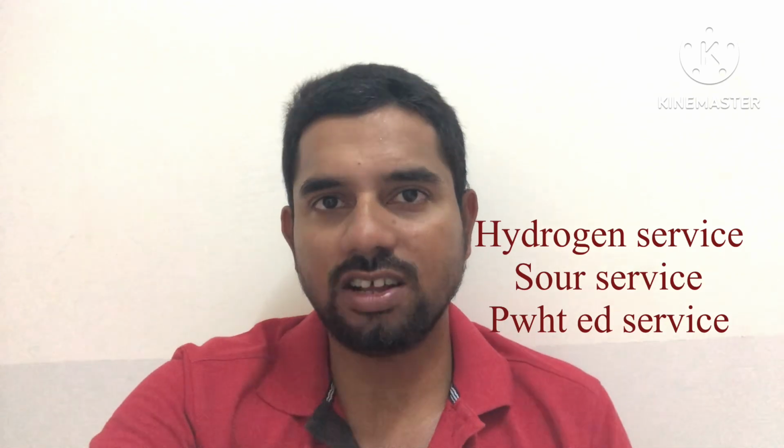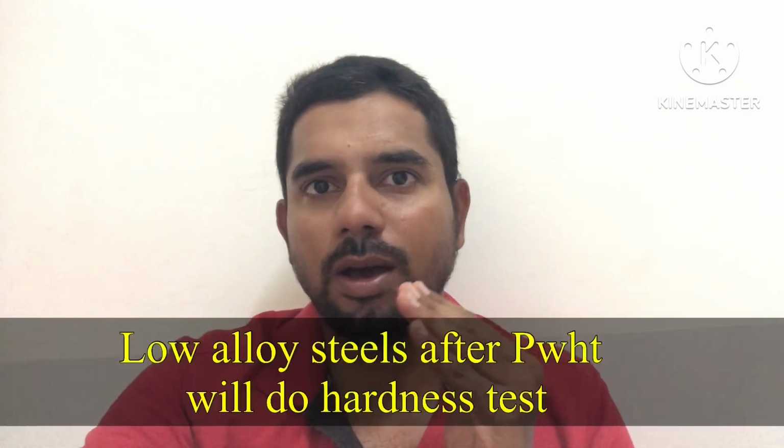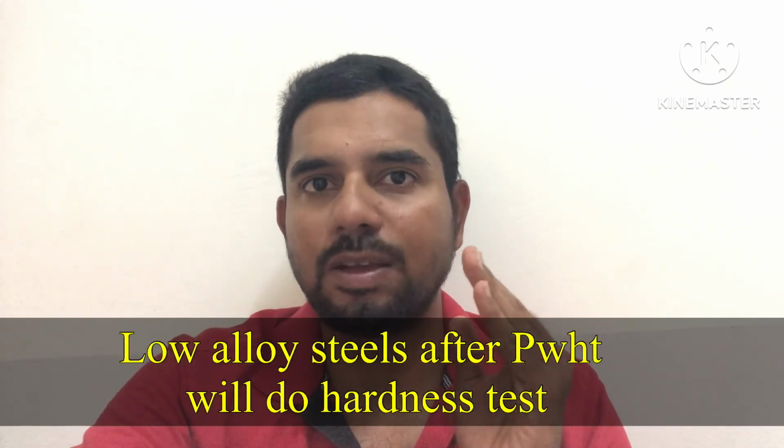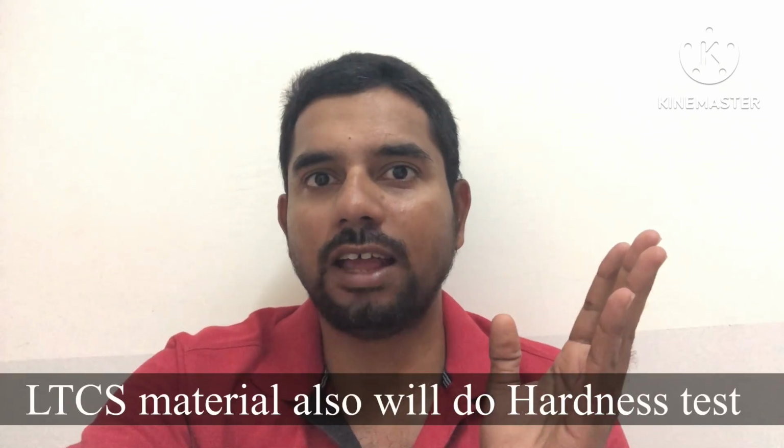When the hardness value is high, the toughness value will be less. All of you know impact property is a very important property of the material. Those with cryogenic temperature service need this impact property. So if the hardness value is more, the impact property will suffer.